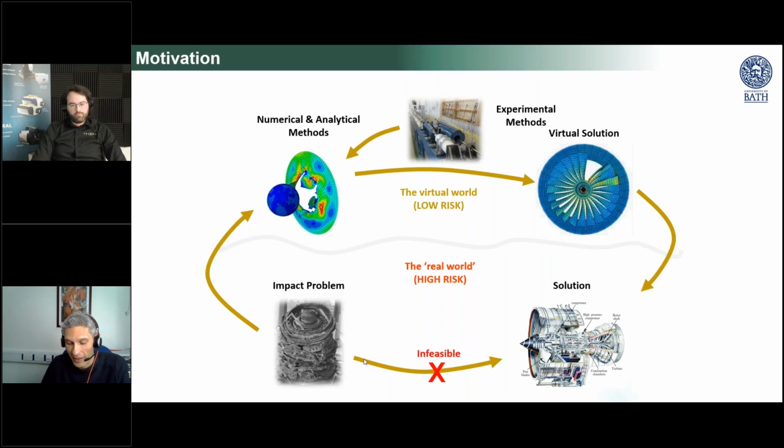And typically, the most common data that we can get for a material come from tensile tests. However, when these tensile tests are conducted at high strain rate, meaning that the material will deform and fail in a time of approximately 200 microseconds typically, the mechanics and other physics, such as thermal properties, become coupled, and the analysis becomes more sophisticated, and some challenges in the analysis of the data may arise.